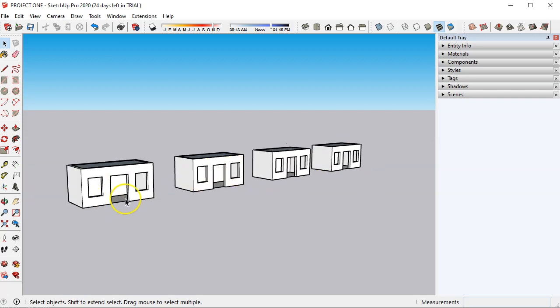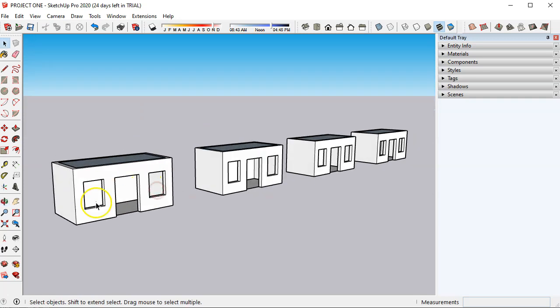And that is one of the basic rules of SketchUp. If you have something two or more alike in a model, then you have to make it a component. And anything you need to change, let's say you made a mistake with something over here, if you correct that mistake, then all of them will be corrected at the same time.